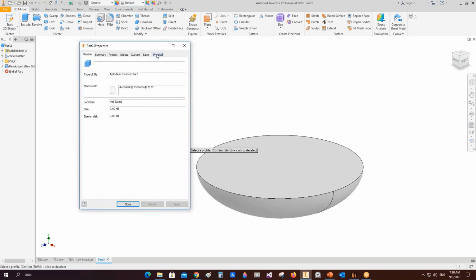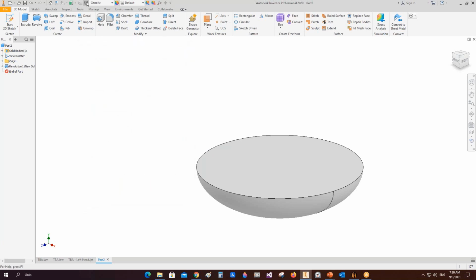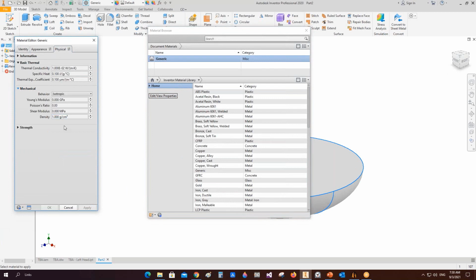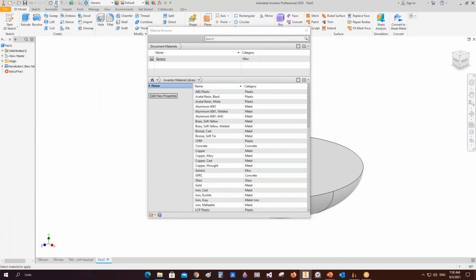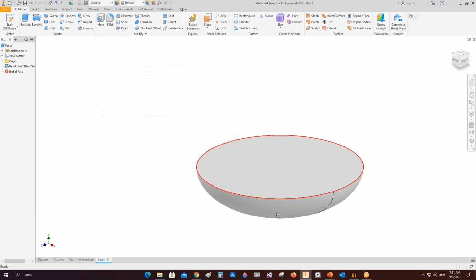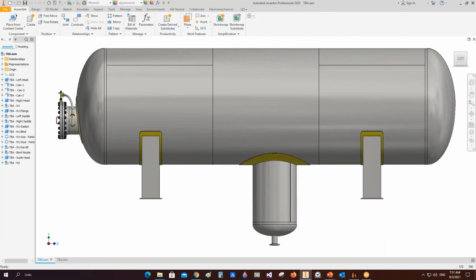So from here, that's the weight of this element, it's around 2 tons of liquid. That's the specific gravity. So if you would like to define the specific gravity, you can, as we discussed, define it here. So let's change it like that. So if we calculate the weight, it will be around 1.6 tons. That's the weight of the liquid. So you can calculate it that way right now. But we are planning to add the liquid level.